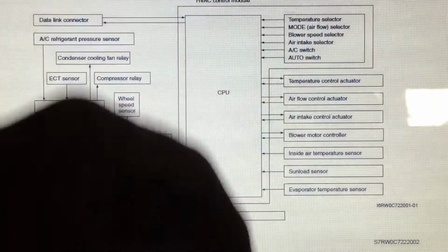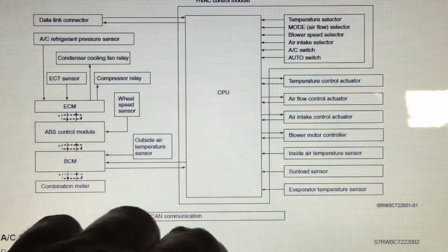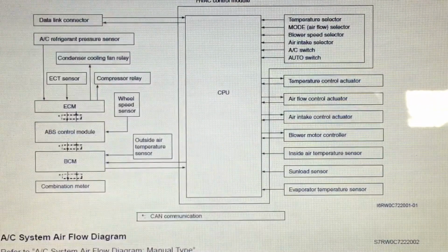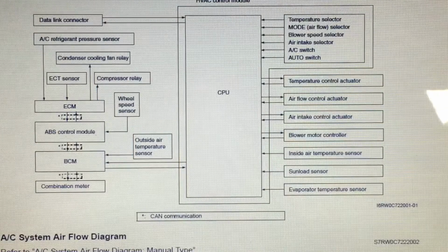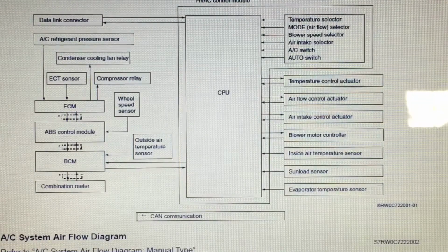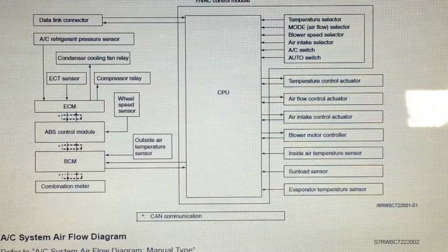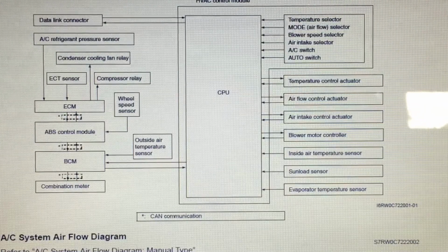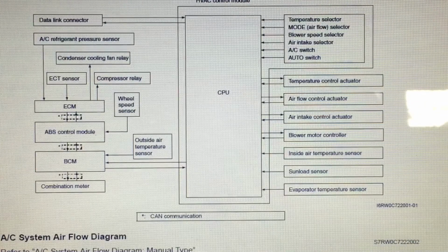Think about that. Go ahead, I'll wait. Anyway, there's two reasons that come to mind. The faster the vehicle goes, with respect to the heating mode, the more air is going to flow through the radiator. So the rate of cooling on the radiator is going to change. The system might want to know that.